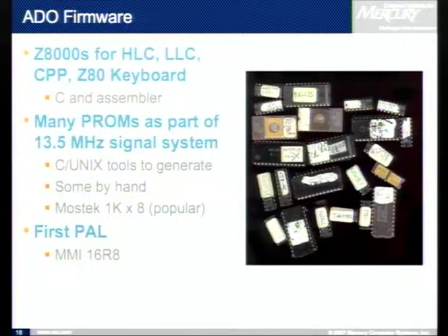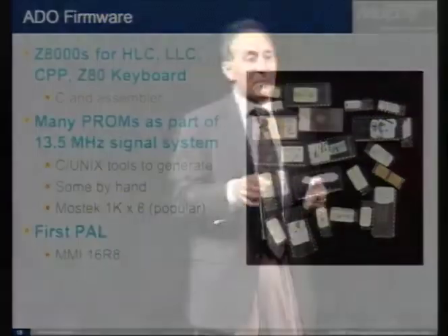Earlier, when I was talking about FPGAs and having to make this 2D spatial design, back then everything was 374s, 2-to-1 muxes, and full adders, and you very statically schedule that machine by drawing it out on paper with templates.